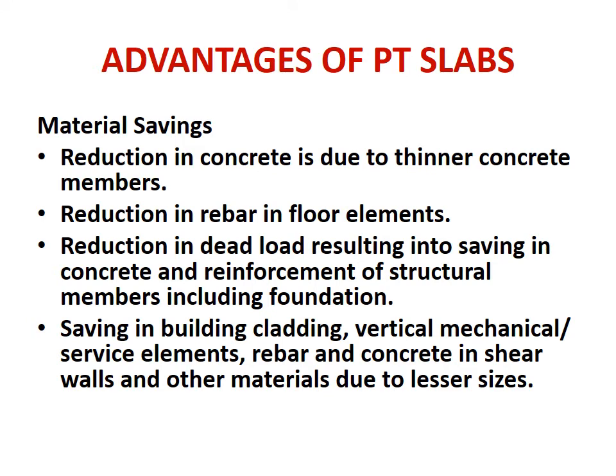Advantages of PT slabs are many, like material savings. There is a reduction in the concrete due to thinner concrete members. There is a reduction in rebar, particularly in floor elements, and reduction in dead load because they don't have beams, they don't have high thickness of the slab, so they result in saving in dead load, and then as dead load is less, there is a saving in concrete and reinforcement of structural members